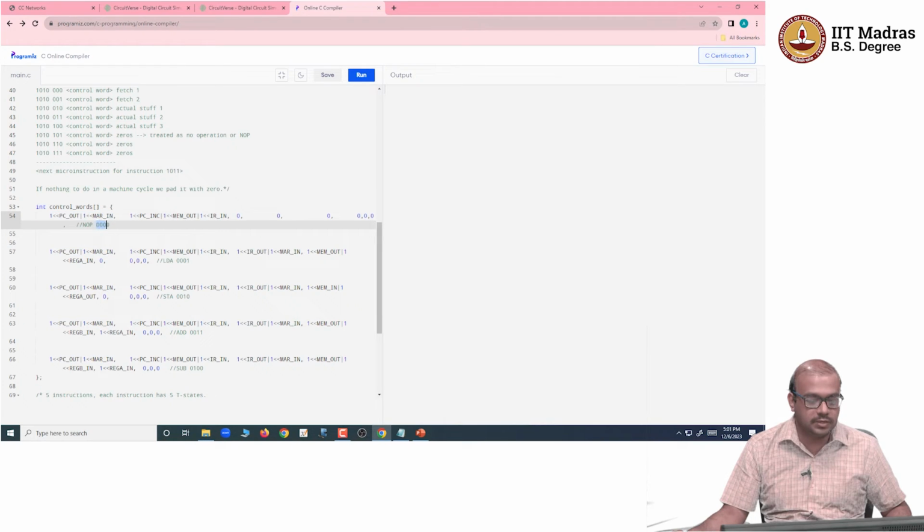Whereas 0 0 0 0 1 1 1, that is the last micro instruction, is going to be representing this, right? The last 0. So this entire thing is basically 8 micro instructions. This is the first micro instruction, second micro instruction, third, fourth, fifth, sixth, seventh and eighth are all zeros.